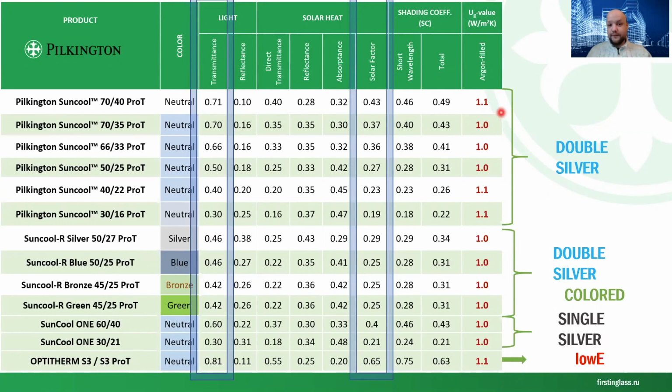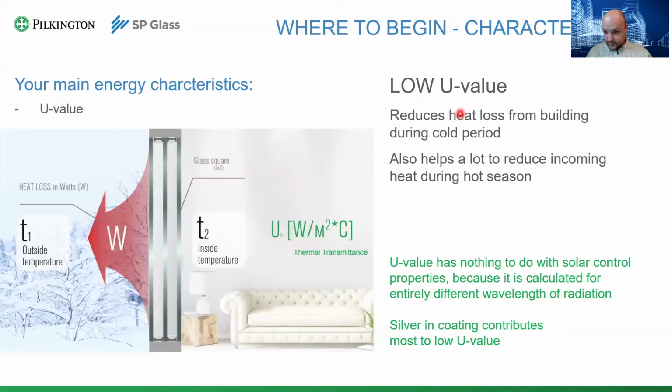For example, if you have specified something like 40 or less solar factor for your vertical glazing, for horizontal glazing I would go for at least 25% instead of 40. Because yet again, for the roof it is much more important, because you will be having much more solar heat on the horizontal surface than on the vertical one. Okay, done with that.